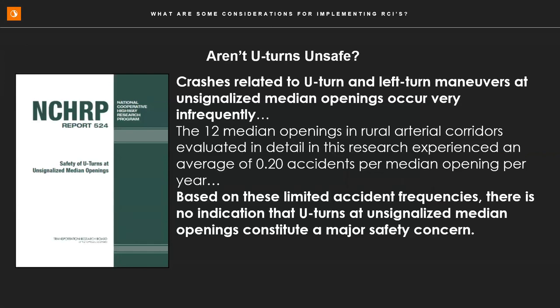Some people say, aren't U-turns unsafe though? The reality is that U-turns are not a major safety concern. The perception that U-turns are dangerous may come from downtown areas which have signs banning U-turns. In those areas, the roadway is tight, and a U-turn maneuver may cause problems with traffic flow, especially if a vehicle's turning radius doesn't allow the movement to be made without backing up in the middle of the turn. However, national and local studies, including this one, have shown that U-turns are no more dangerous than normal turns from median divided roadways. Super streets, or RCIs, are designed to accommodate U-turns at appropriate locations.